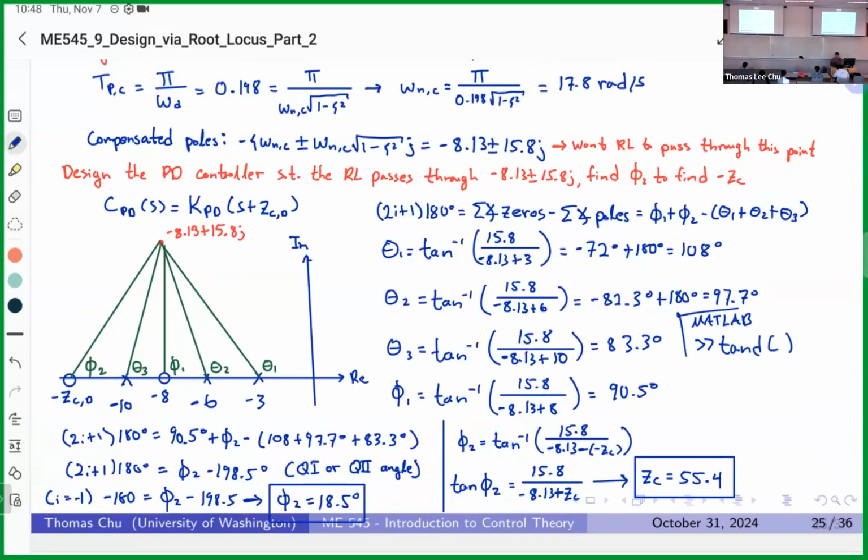All right. So I'm not going to include the PI controller part of this because all we have to do now is just add a pole at the origin and a zero close to that pole, so that we can just do directly on the computer. But we're pretty much done. So PID controller design is mainly designing the PD controller part and then just adding the PI component next.